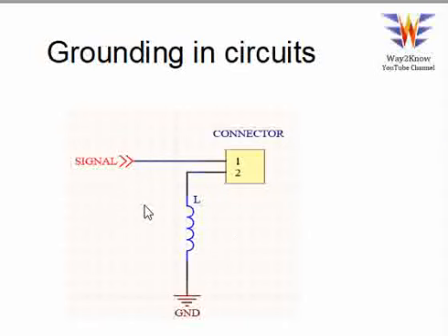When the inductor is present here, we know that it doesn't allow high frequencies to pass through. It might not be an inductor, it could be a ferrite bead also here in some cases. So if there is any high frequency noise on the board, which might cause EMI, EMC concerns for us, those will be blocked by this component.